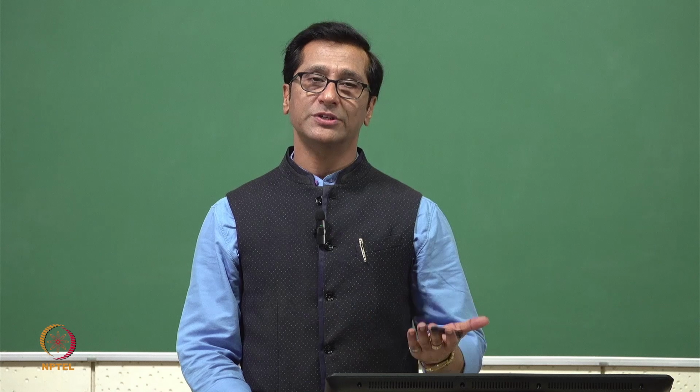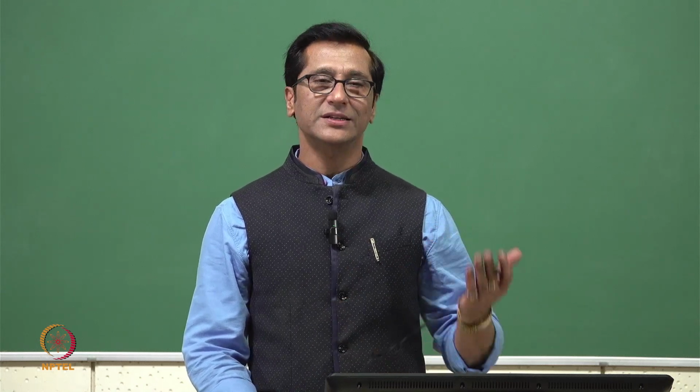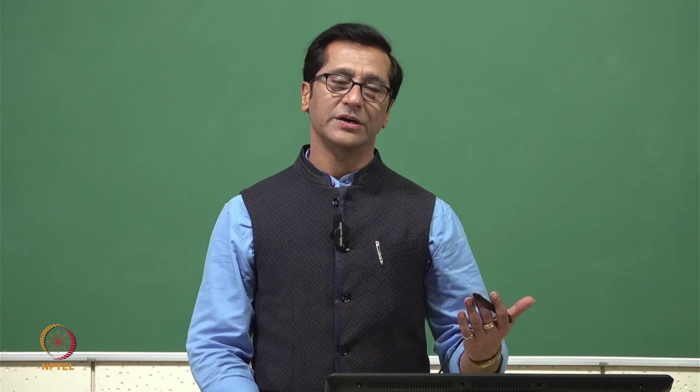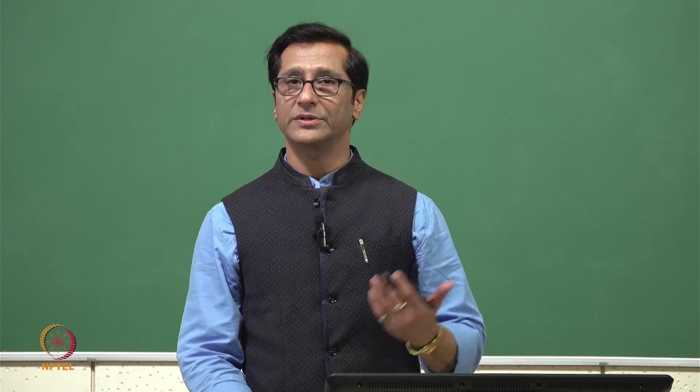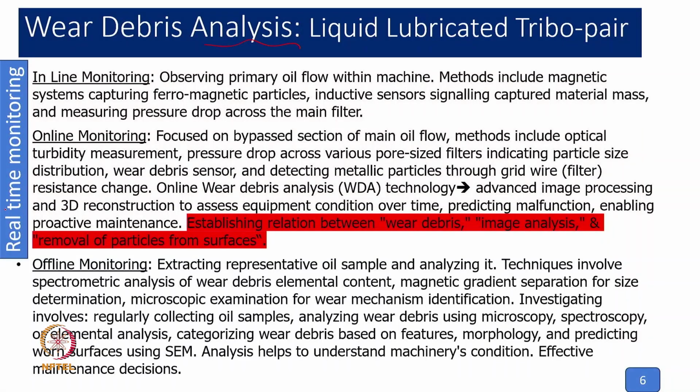Now coming to a little more detail, initially we gave some glimpse of dry lubrication, and we felt that dry lubrication is still not really dry, reason being there is some oxide layer on it. At low or high temperature, at lower or higher load, there are oxide layers, so they act like a lubricant. Now coming to wear debris analysis, we can divide it into three domains. Of course, mainly two: real-time monitoring, which we call online monitoring, and offline monitoring.